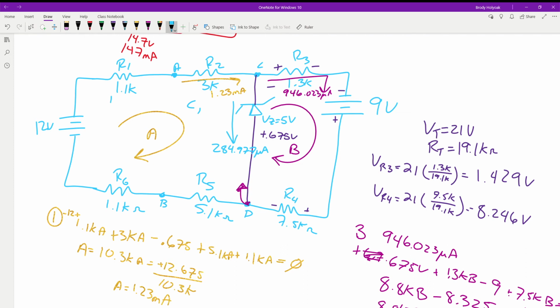How much? Okay. How much voltage do we have across R6? And that's one reason to look at, can you shorten the number of calculations? You're going to have positive to negative voltage this way. You're going to have negative to positive voltage this way. So we start at point A, we come around. So we have a negative 1.353. We have a positive 12. We have a negative 1.353. That all has to equal 0, which is what we're looking for.